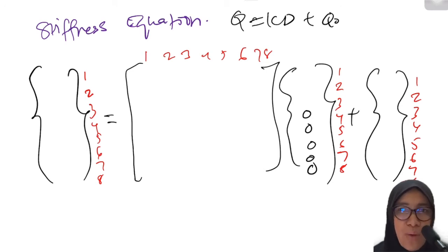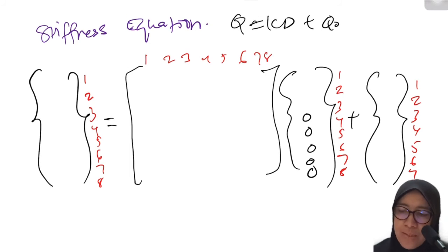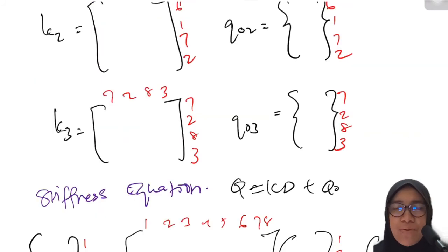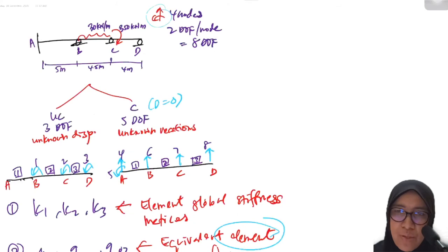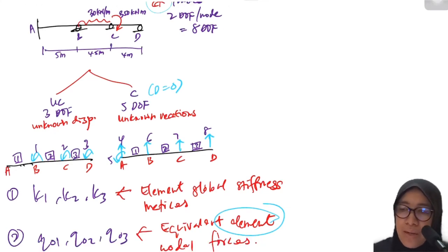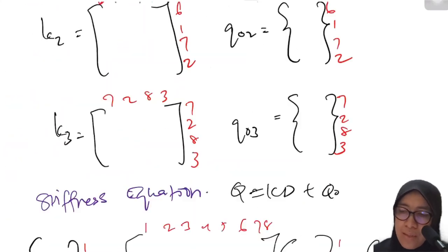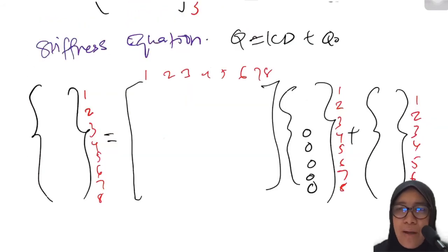This is the reason why I always advise my students to start with sketching the diagram according to unconstrained and constrained system, because we solve for the unknown displacement by only considering unconstrained system. In full, when there is no settlement, the value times 0 gives 0.